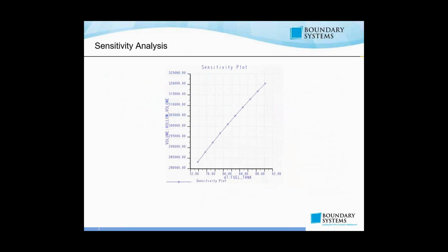It'll also show you a case where there's a nonlinear relationship between your design objectives and your variables. In other words, if there's a parabolic relationship between them, where it starts low, then goes high, and then comes back low, then the sweet spot is going to be somewhere in the middle rather than just going from zero to high. So you can start to tell the relationship between your design inputs and your objectives using these sensitivity plots that Creo generates for you.